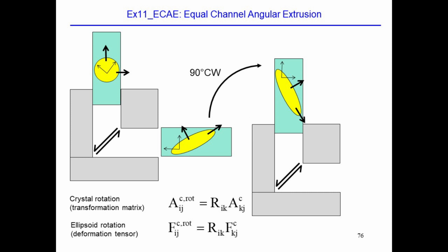And sometimes the sample fractures, so they have to put a back stress. They also put a plunger on this side to create more pressure in the sample. There are a lot of practical issues, but eventually people have managed to make magnesium, aluminum and titanium components that they have used for building small pieces like prostheses, like the screws used to hold bone fractures, things like that. But in general, very small pieces.